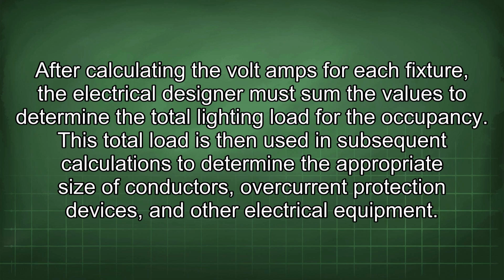After calculating the volt amps for each fixture, the electrical designer must sum the values to determine the total lighting load for the occupancy. This total load is then used in subsequent calculations to determine the appropriate size of conductors, overcurrent protection devices, and other electrical equipment.